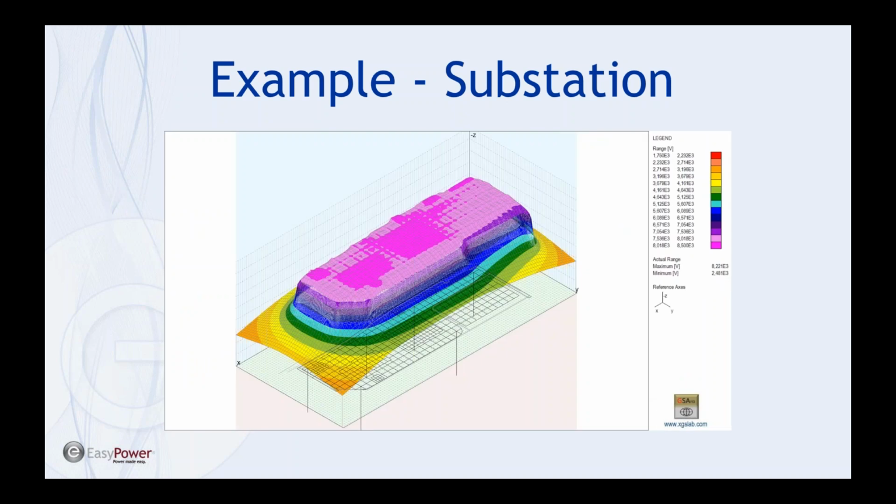This visual shows the ground potential rise with the proposed grid design. This is during the design fault that we've applied in the soil model that has been applied with the preliminary grid design that is shown below. You can see the grid and some ground rods that are going down in the Z direction from the grid. This is a nice visual because you can see that the grid area, the elevated area in pink on the GPR chart, is brought together up onto an equipotential plane.